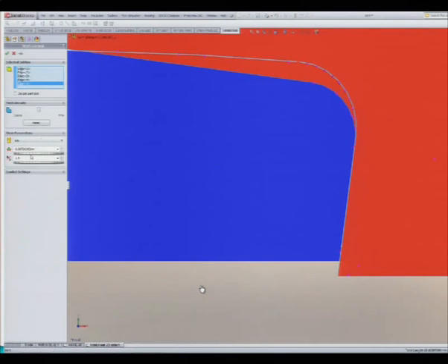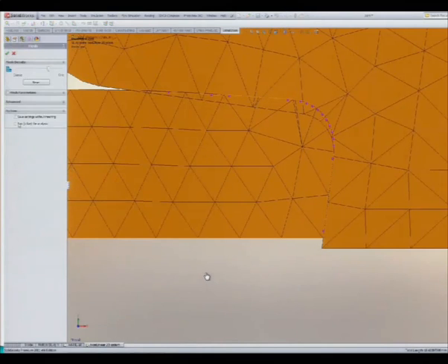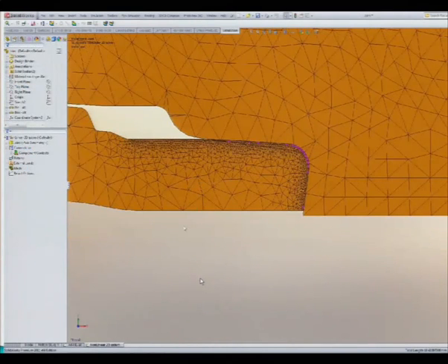You can download again this exercise from the SolidWorks website. And the control mesh that I include is 0.07 millimeters. So it's very small, and this is the reason why it was impossible to run in 3D. Imagine in 3D running this is more than millions of degrees of freedom. Impossible, right?